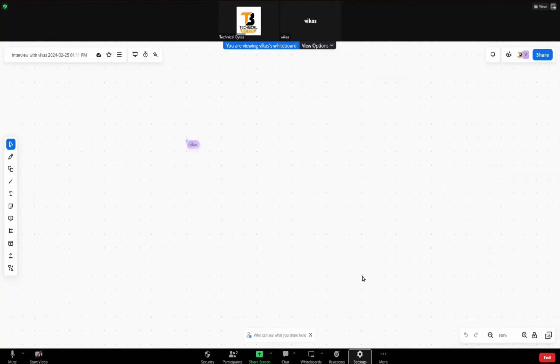What is clock tree? Clock tree goes from the source point to all the flip flops. That is called the clock tree, sir. The input clock may come from a PLL or a clock generator, going to all of them. I agree. But if your tool is allowing us to connect the output of any flip flop to the input clock of the second flip flop, then why do you think you are breaking a law?